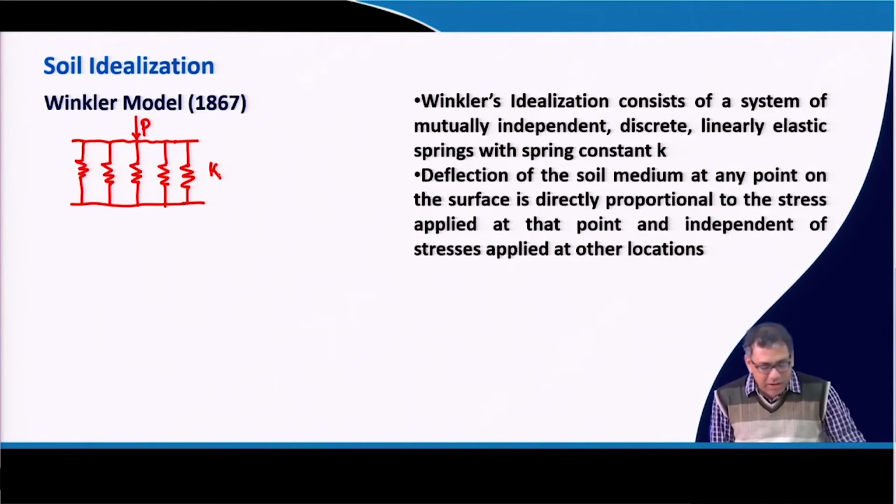Okay. So, in this Winkler model the soil is replaced with springs, whose spring constant is K, but these springs are not connected to each other, they are discrete, and the spring constant is linear, that means a linearly elastic model. The deformation of the soil media at any point on the surface is directly proportional to the stress applied on that particular point, and it is independent of the stress applied at the other locations.